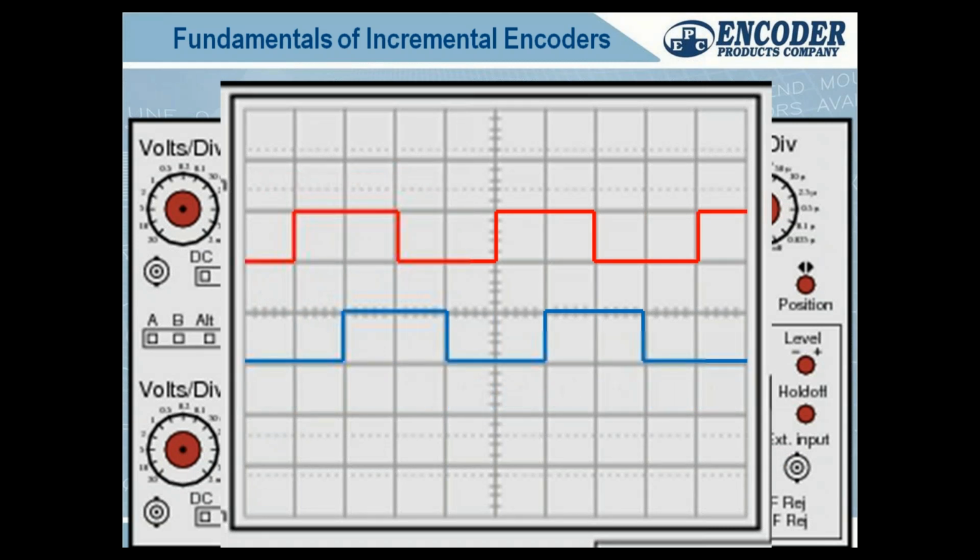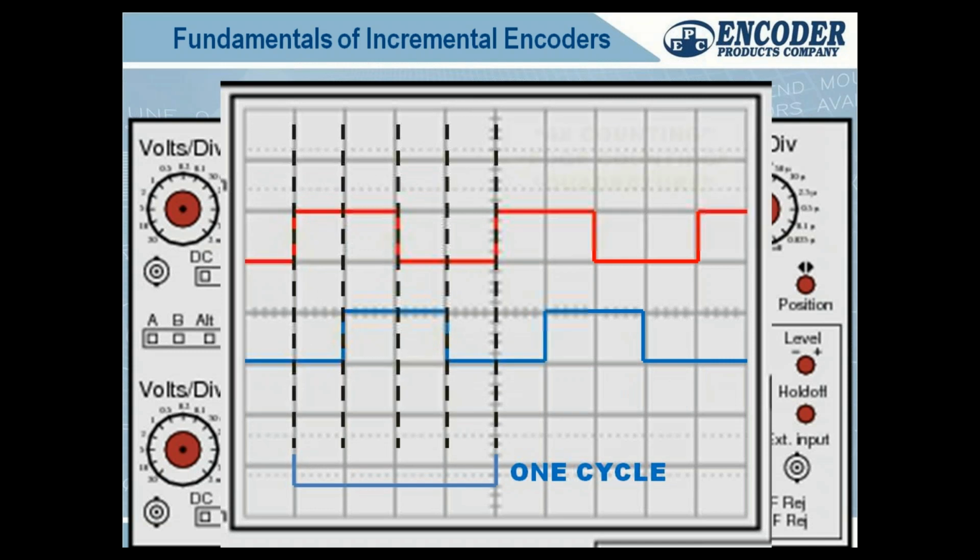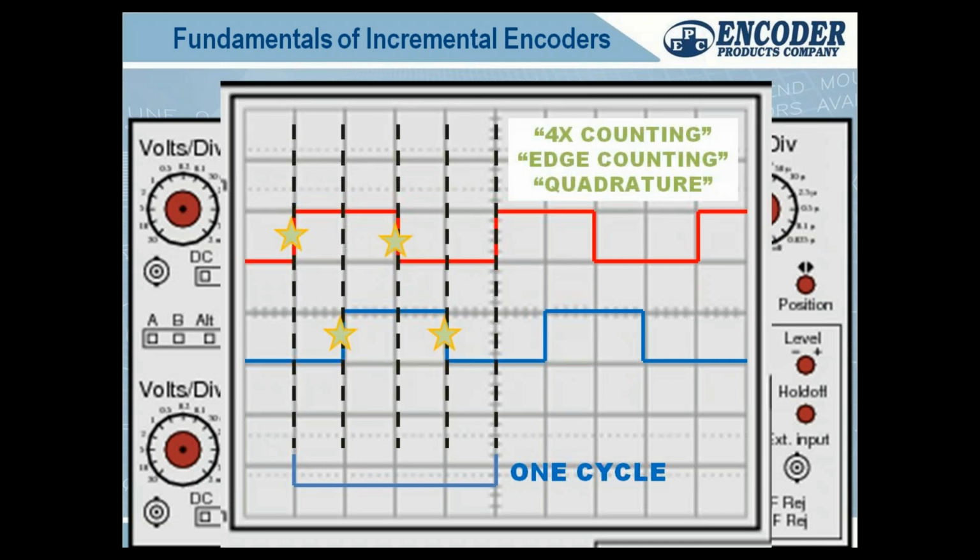Once that happened and people developed this two-channel output with the offset there, they realized, well, if we offset that 90 degrees, we can actually take these channels and looking at A, we have a rise on A, and about 90 degrees later a rise on B. If we look at one wave from rise to rise again as 360 degrees, on a data sheet, you'll see that referred to as electrical degrees versus physical degrees of the encoder shaft. This is called electrical degrees. So we have one pulse is 360 electrical degrees.